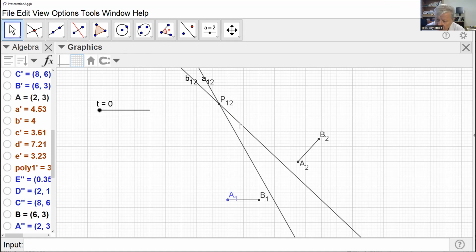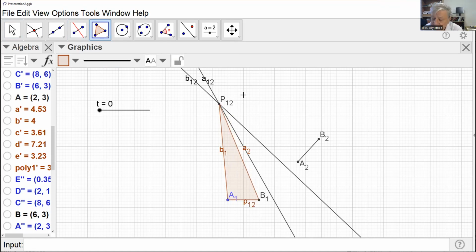Now, he says that you can rotate this rigid body to move from the first position to the second. Meaning, if I rigidly connect that AB, that rigid body, that plane, by attaching a revolute joint at P12, I can rotate this rigid body from the first position to the second.